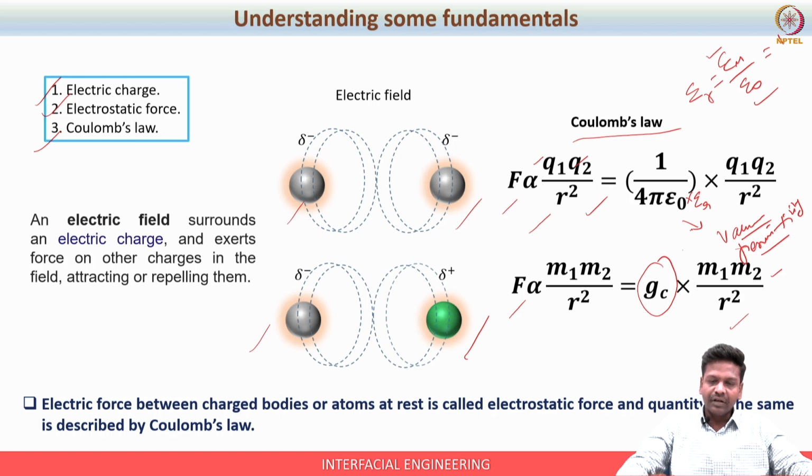So this is nothing but, we are just trying to verify the unit. This will be Coulomb square by meter square into E naught. In the denominator, E_R has no unit, and E naught, as we have just seen, is nothing but Coulomb by volt into meter. So it will be volt meter by Coulomb, because it is 1 by E naught.